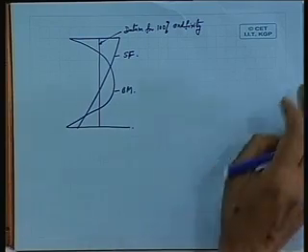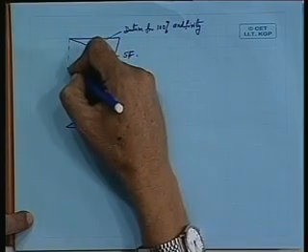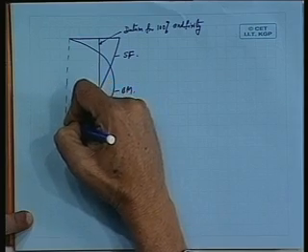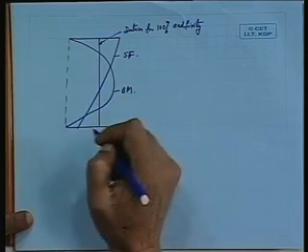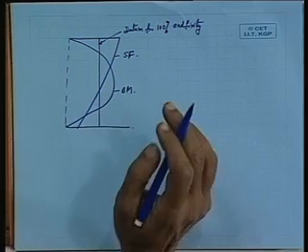Okay. Now, let us try to see what happens if the two ends were supposed to be simple support. If the two ends are simple support, then the bending moment should be 0 there. So, if the bending moment is 0, then if you join these two lines and start measuring the bending moment from this datum, then they are 0.